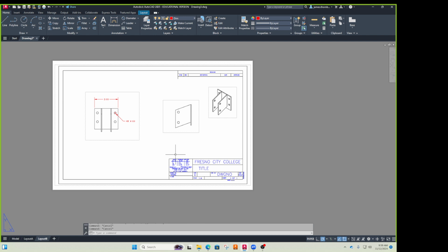So I could draw a line here in paper space, and then move it from that corner to that corner, right? Or I could use tracking to do the same thing. There's also another command where you do it by picking on stuff in the viewports, but I think that's easier than doing the other way.